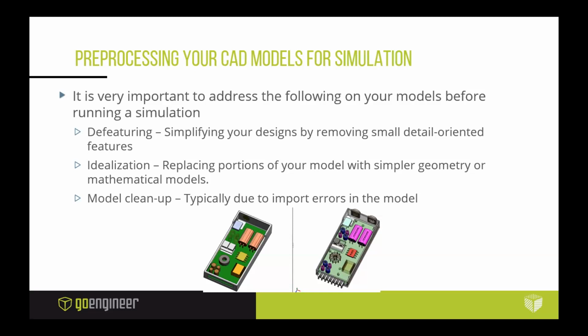And I asked for help, and they said, "Oh, you're an application engineer. You should know how to do this, Enrique." So I had to figure it out. What I was missing is I had too much detail in the model, and that's huge. Simplifying and conditioning your CAD models for simulation is an essential part of this whole workflow I'm talking about. So there's a couple of things you want to do when you're going to run the model, and they're up here on the slide. Defeaturing is the main thing.